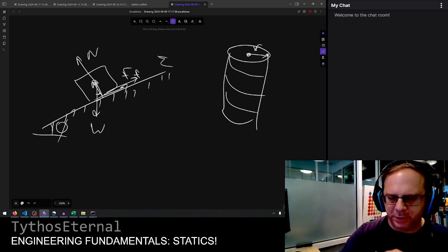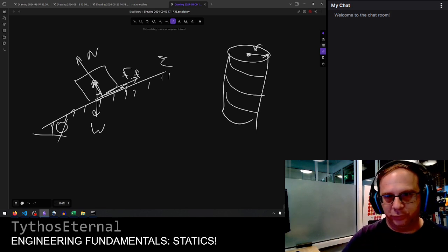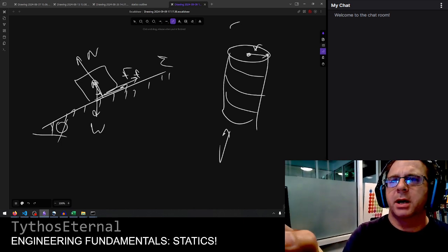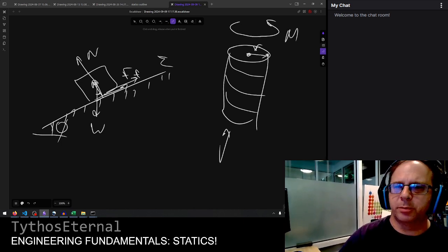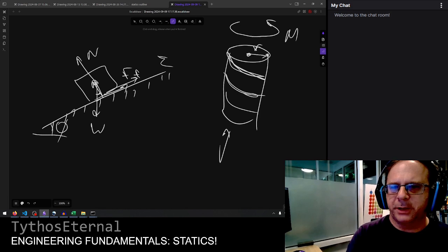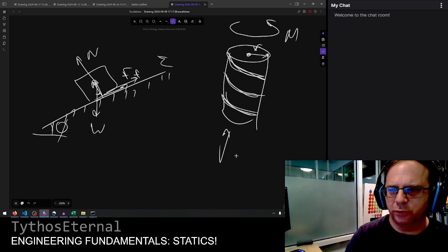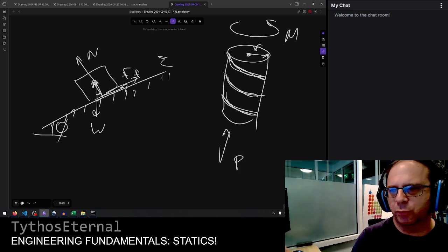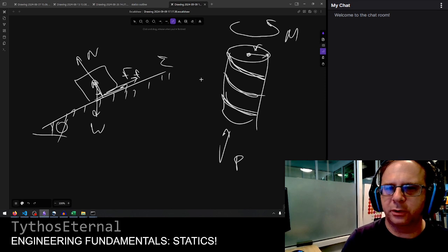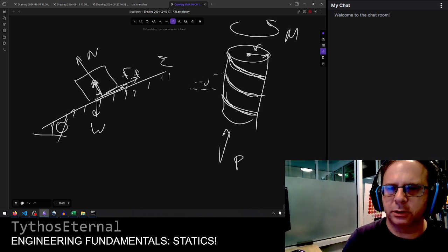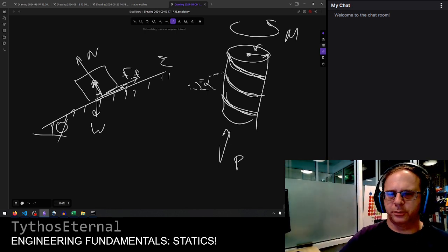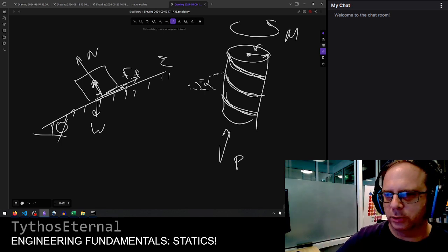So there's a screw that might be binding to surfaces or elements or what have you, but it's bearing a load. And it's bearing a load by effectively applying a moment and translating that moment into using the force of friction about that ramp as a means to resist or bear the load. So it will have some radius, and there will be some pitch angle of these threads. We'll call that alpha. So the smaller the alpha, the more threads you need to go around.